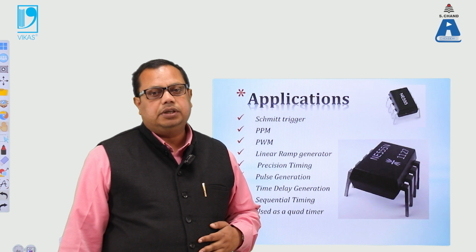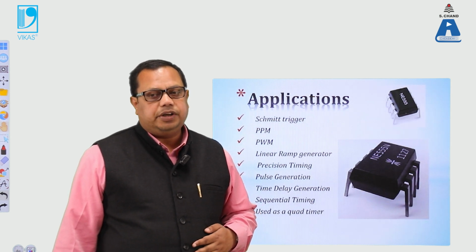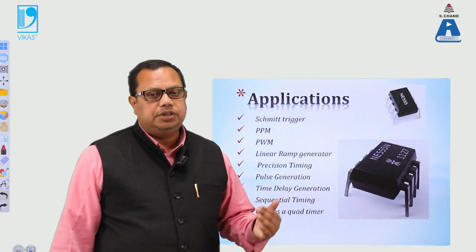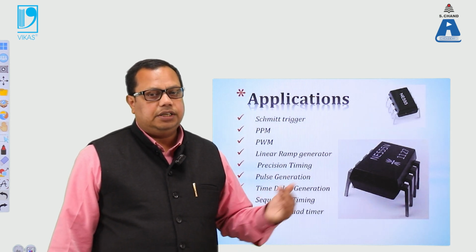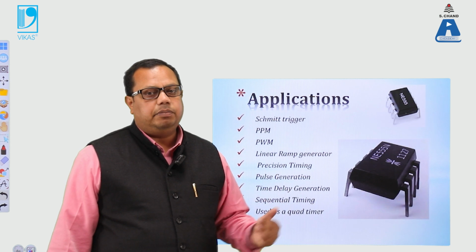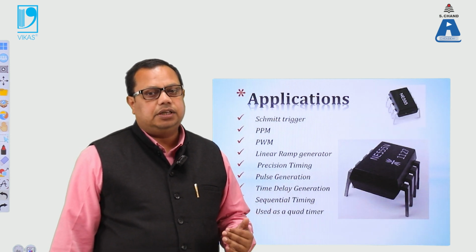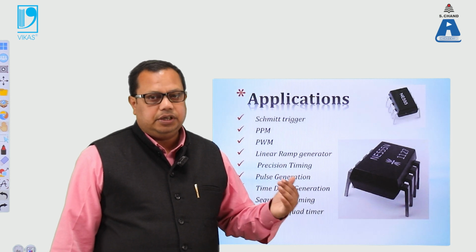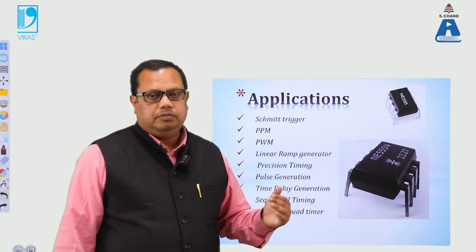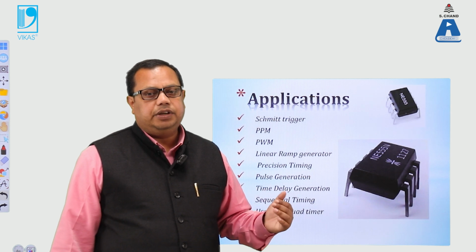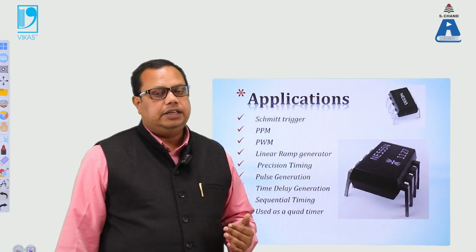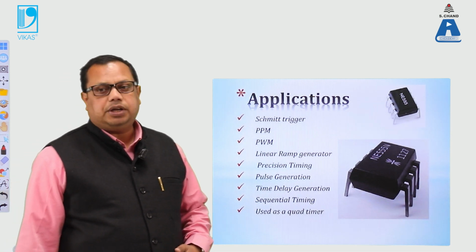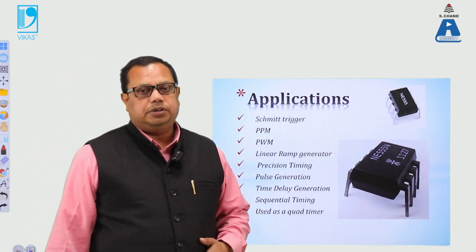Again, to sum up, from the pin configuration to the functions of the different pins used in the IC 555, we then vary the 555 and use it in different modes, monostable, bistable, astable, with the particular circuit diagram when we are using an op-amp, and using that as a flip-flop, and then these are the applications of the IC 555. Hope the concept of IC 555 is more clear from this video.